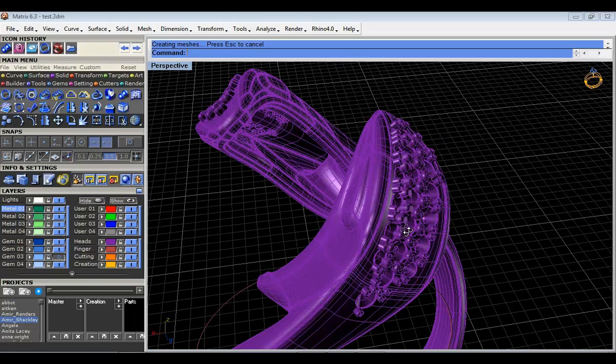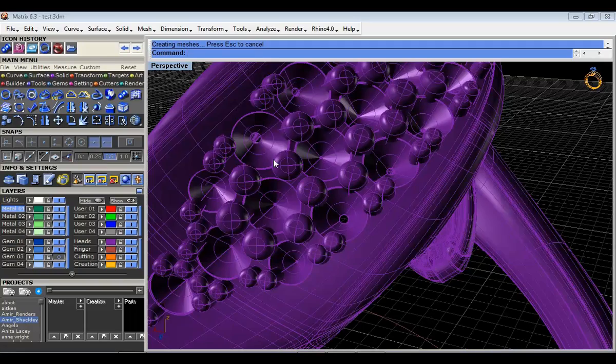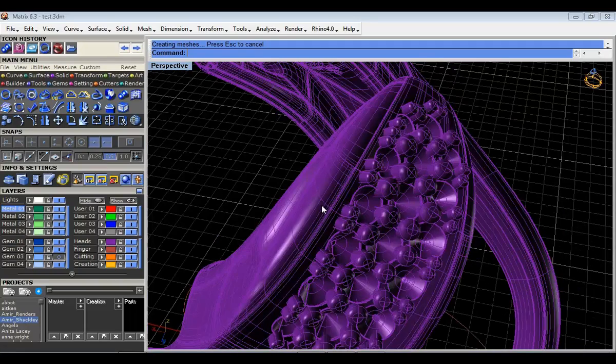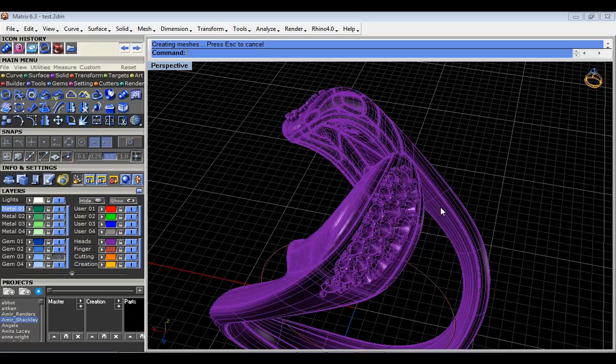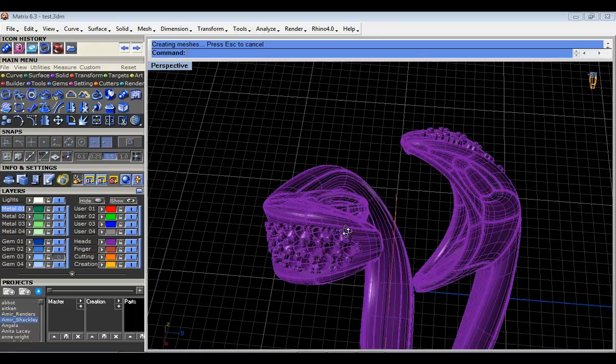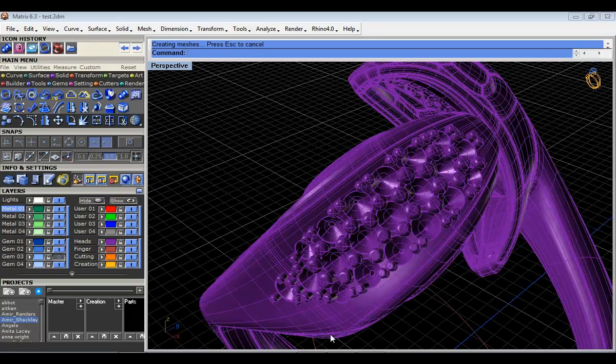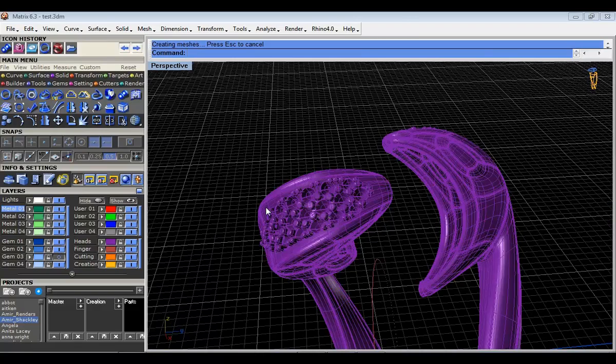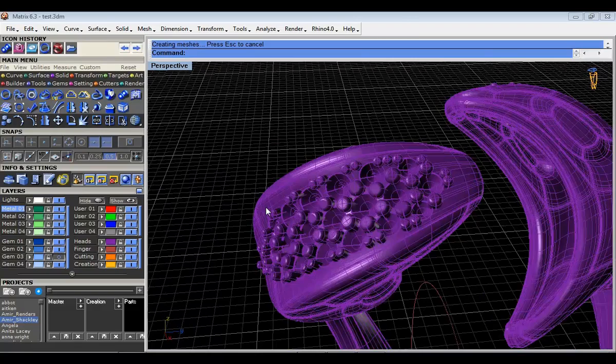So as you can tell, because it's now a Rhino surface, there's your high precision seats all being cut for your stones. You with me now? You could have, in T-splines, subdivided this surface maybe 5 or 10 times. You could have gone in and tried to round off all those subdivided surfaces, and then tried to extrude them downwards, and I think you know what I'm talking about, that's 10 hours work to do something that took 3 minutes.